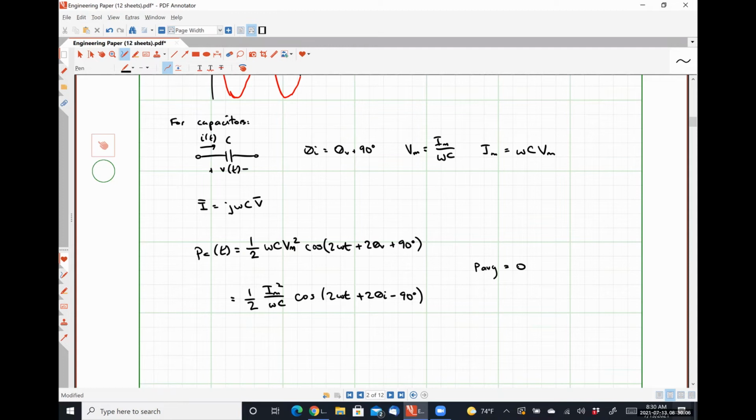All right, so instantaneous power and average power. Fairly straightforward, other than that pesky trig identity. And then we've gone through and we've used our frequency domain relationships to be able to express the instantaneous power and average power in terms of our phasor quantity, so that we can still do all of our circuit analysis in the frequency domain, where things are, well, I would say nice and easy, but they're definitely easier than doing things in the time domain.